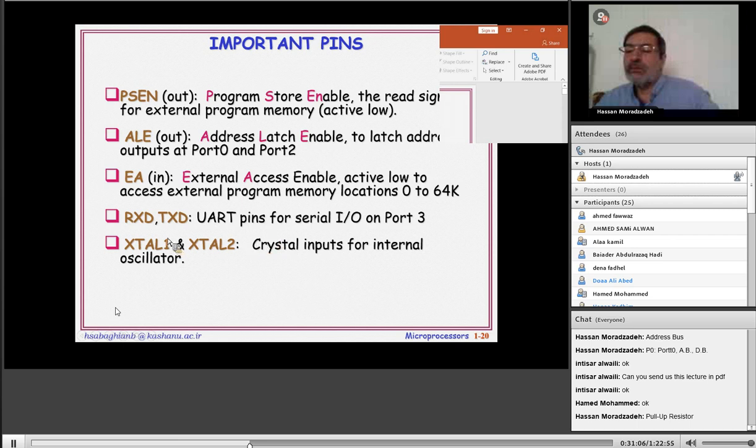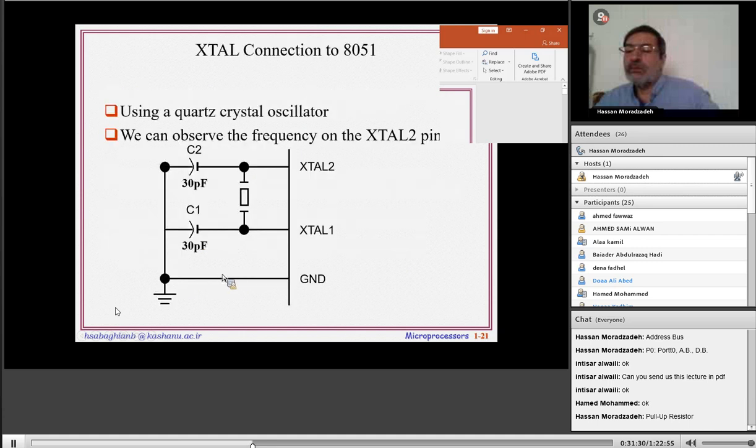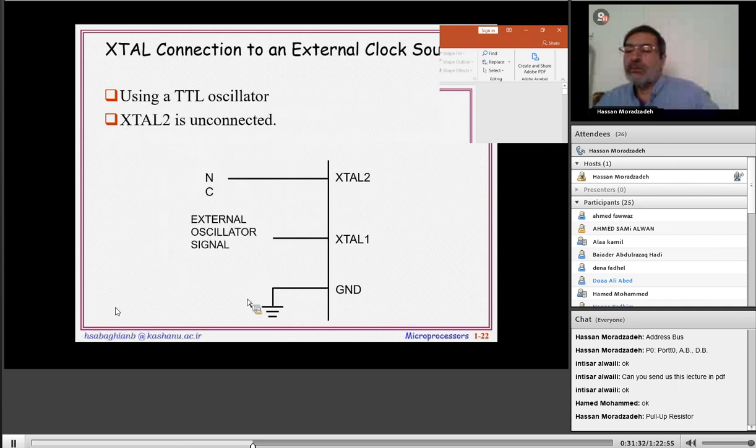For example, computing some machine cycles. For example, if we had installed 11 megahertz or 16 megahertz, okay, find the machine cycle for these items. In this microcontroller, each machine cycle consists of 12 clock cycles. Okay, that means this frequency is divided by 12.